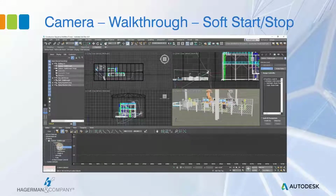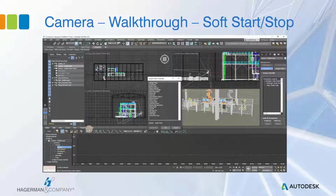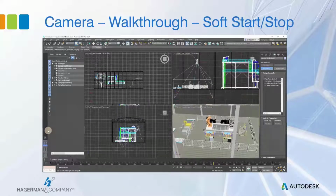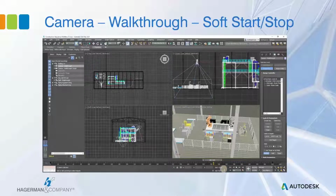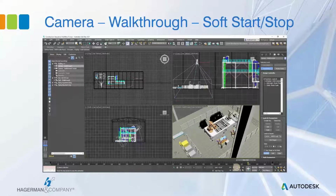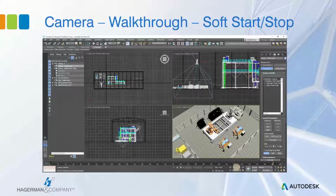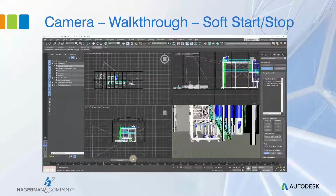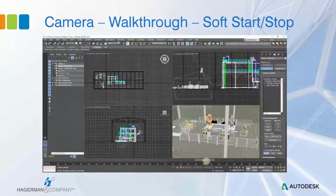Right click on percent, assign controller, and apply the Bezier float. Click OK and then close the curve editor. That's it. We don't need to know what a Bezier float is. We just need to know that when we apply it, it allows for smooth acceleration and deceleration at the beginning and the end of a walkthrough.